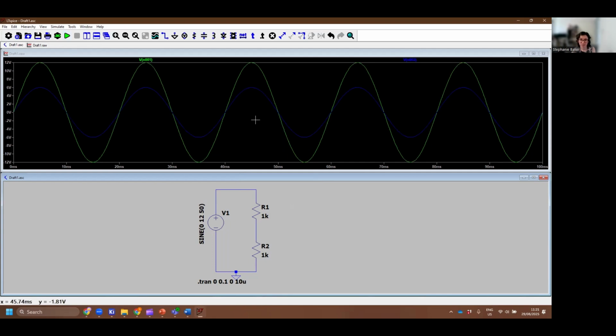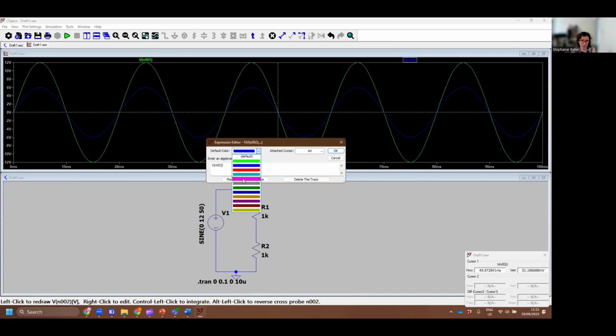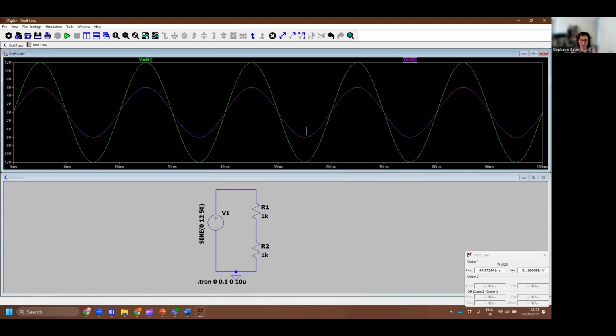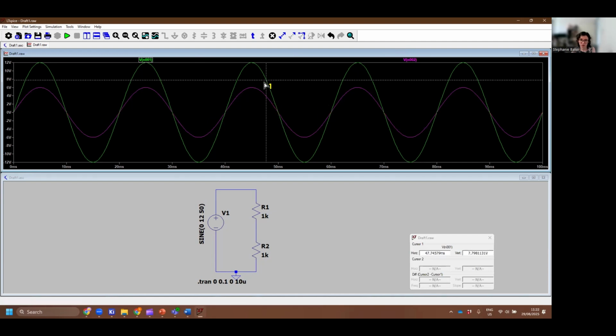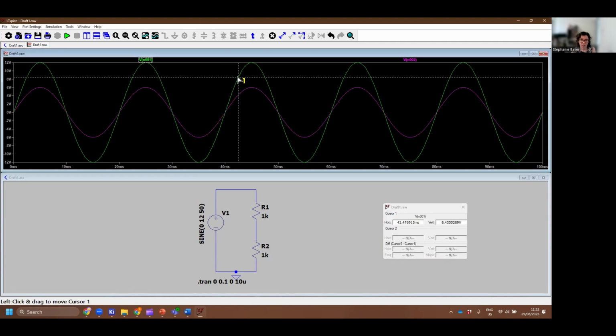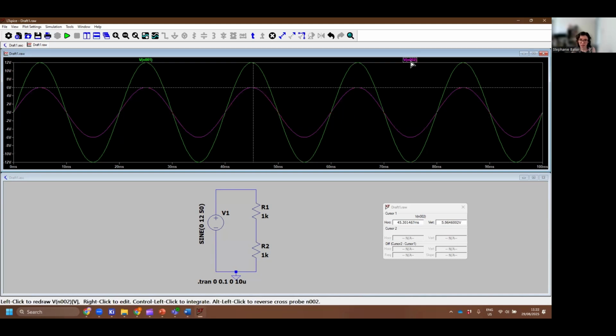So you can see there that that peaks. Actually, you can't really see because it's that awful blue color again. There's a better color. So you can see that we now have half of the voltage that we had originally. In this case, the values are clear to read because they are exactly at a whole number interval. But if you wanted to take a closer look at what the values are, you can select whichever trace you're interested in, and it'll add a cursor. That'll allow you to drag through, and you can see in this little window down here that it's changing where it's looking. So yeah, you can do that by clicking on either of them.